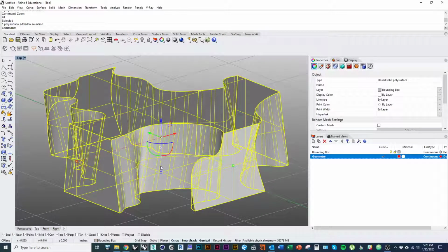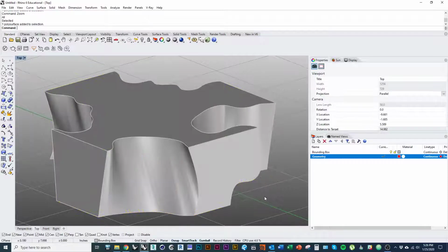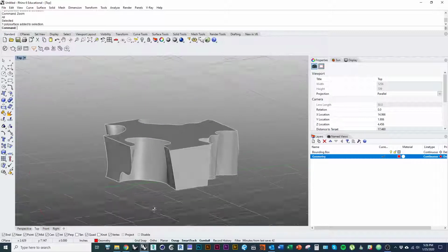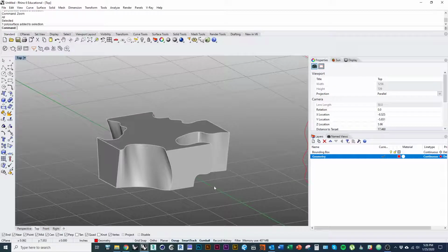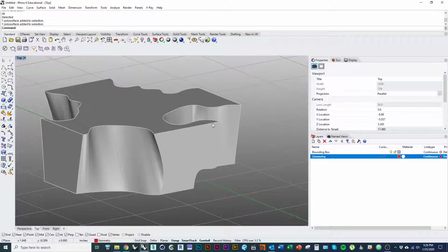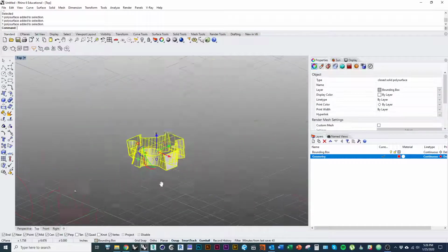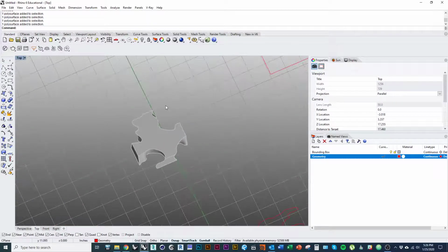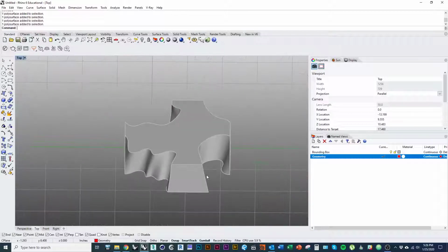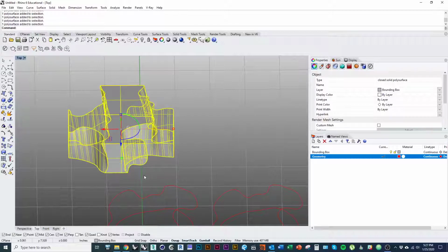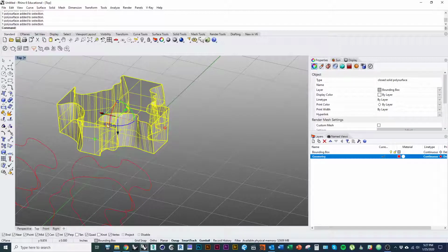like I would want to leave it in this orientation, because if I flip this guy, you can see right there, because of the way that geometry is kind of branching out or hanging out over space. If we were to print this module in this orientation, we would find that the print would fail, because this part of the geometry would start just printing out in space. So again, one thing to test before you get too far with any one geometry is how printable is my shape, right? And there are things you can do to make that printable, right? I could add some support underneath there in order to hold that guy up so it can start printing when it reaches that level.